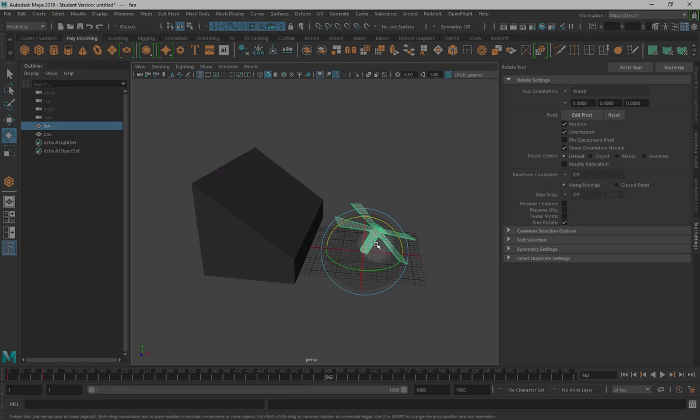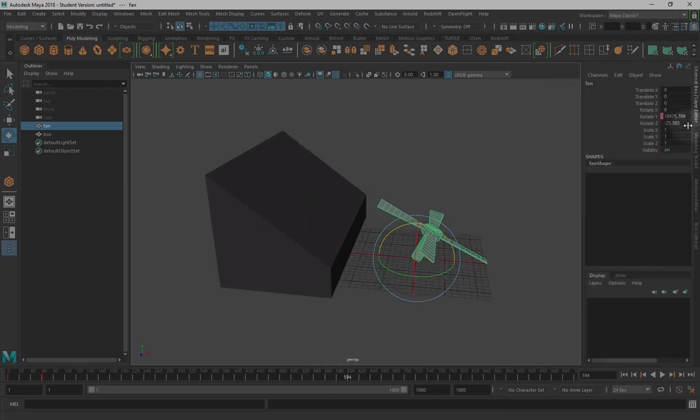If we're rotating the object directly and it's already animated to be rotated in this way, we could end up doing something to it which will wreck the animation. So it might not be a good idea to do that. That's especially important if we've got all of our channels keyframed. I deleted the keyframes that I didn't need, and ultimately that's allowing me to use this particular rotate setting to get the object to sit at that angle.